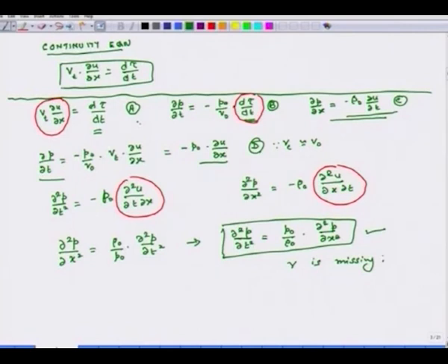And once again we notice that gamma is missing from here, gamma is missing from this case, and what that means is that the system is isothermal, and that is why gamma is missing, and this is how the sound is going to get propagated if sound propagation was a purely isothermal phenomenon. And the other thing we had to find was what is the value of C.